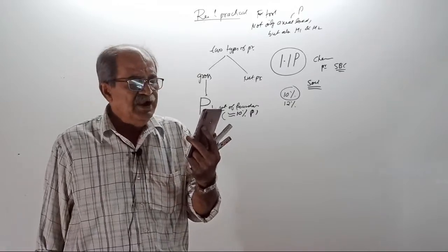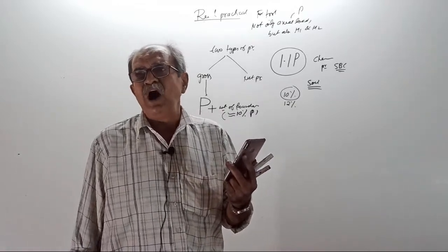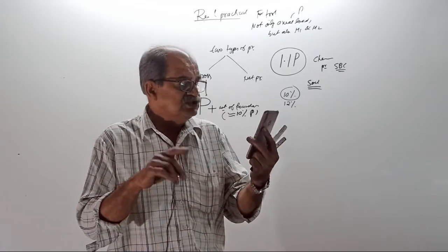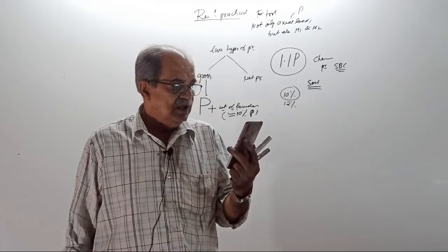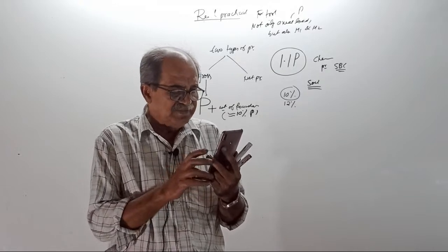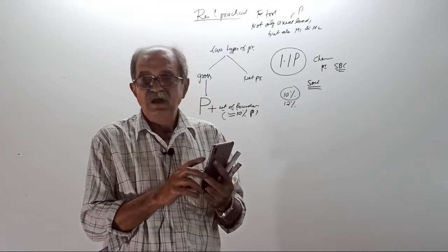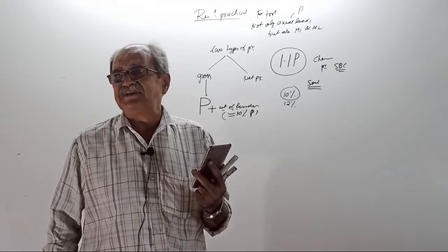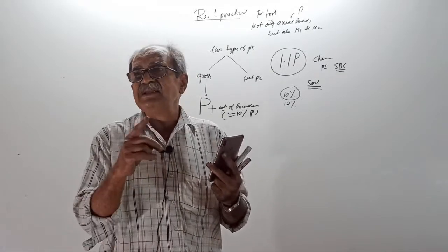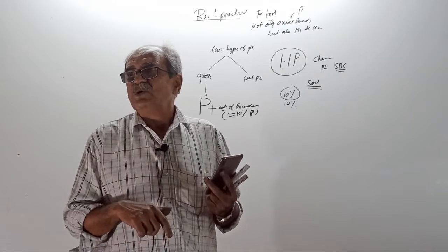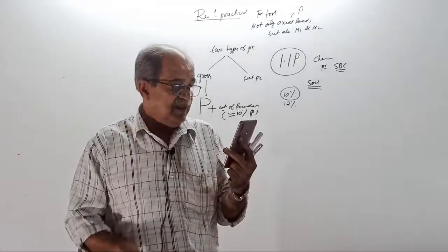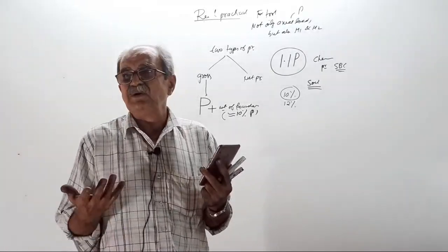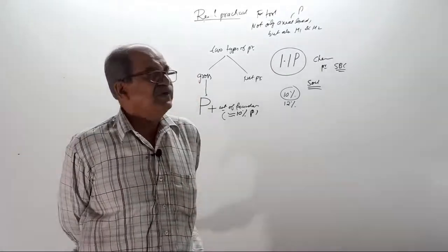Because finally to the soil, not only column load, weight of footing also will go. Shall we consider gross pressure or net pressure when we consider soil safety? You are not answering. This I told you earlier.